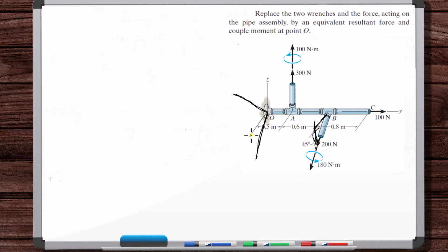You have a moment about the x and a moment about the z, which creates this resultant moment that's perpendicular to the parallel force couple moment, right? You actually wouldn't need to find the moment about the x and z. You would just say 200 times this moment arm distance from this axis. That's the rotation it's causing about this axis.